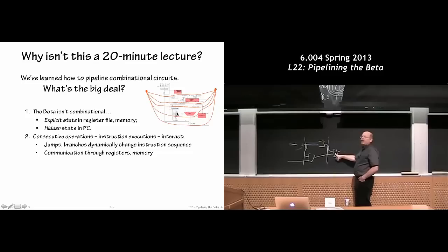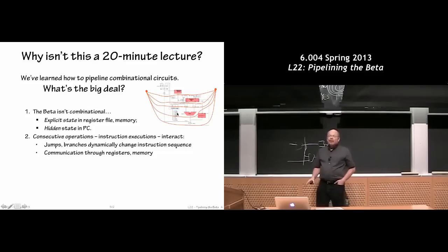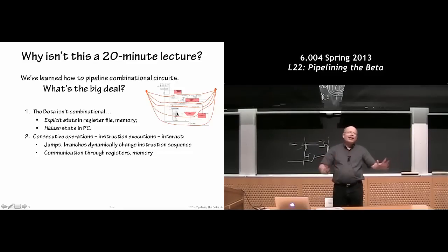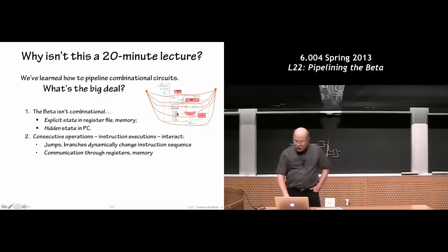If this guy is writing into the register file and this guy is reading from it, then there's information that's flowing not strictly downstream in these simple diagrams. If you think about what wires go backwards in this diagram, you can think of the branch offset wire, working here in what looks like the second stage, passing information backwards up the pipeline.